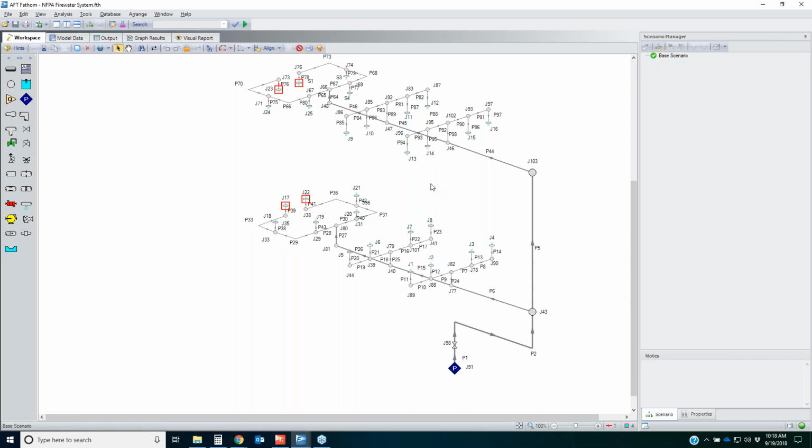So this is where, if you're doing things by hand, you're going to have to do a lot of extra calculations to go in and figure out which spray nozzle is actually hydraulically the most remote. The reason why is because your piping diameters are changing throughout the system in different ways. Your pipe lengths are changing. You've got different fittings and losses in there that you have to deal with. So there's a lot more complication that makes it more difficult to figure out what you actually have.